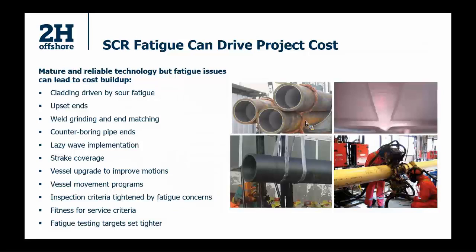Okay, so SCRs are great, but SCRs can also drive your project costs if you're not careful. SCR fatigue is typically the driver of these costs. Because of our analysis methods and the design conservatisms we use, sometimes we can end up with costly solutions such as cladding, for example, which is going to add millions of dollars to the project, upset ends, superior welding, and counterboring, etc. Even the lazy wave implementation, the SLWR, is a cost item. Then sometimes your vessel might be dictated by your riser, at least partly. So there are a lot of items where we can increase our costs.